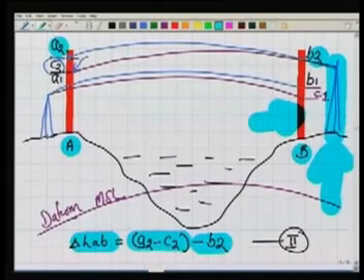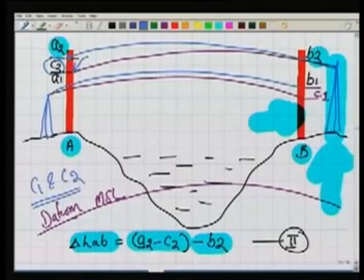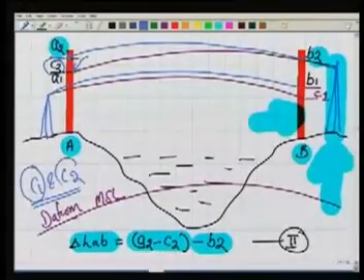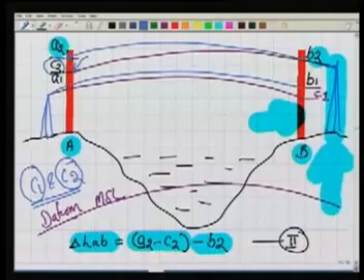Well, one thing is very important here. How about the values of C1 and C2? This is important, if we are taking these observations simultaneously. The meaning of simultaneously is I have one level kept at A, another level kept at B, and we are taking the observations simultaneously, so that when I am taking the observations, the atmospheric condition for both these observations is the same. In that case, we can very well say that C1 should be equal to C2. These two errors should be the same.